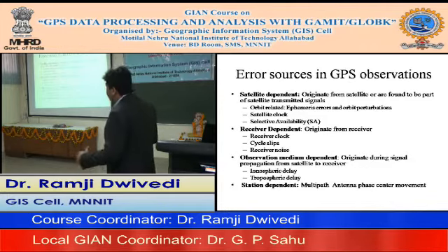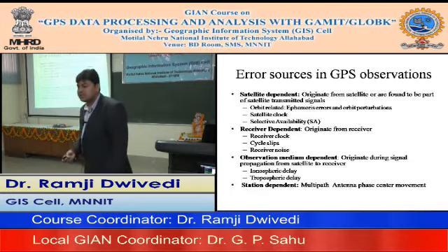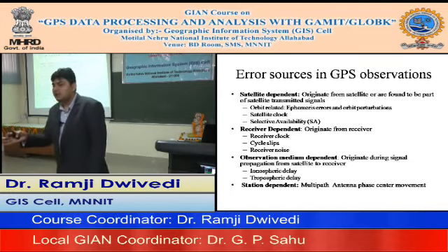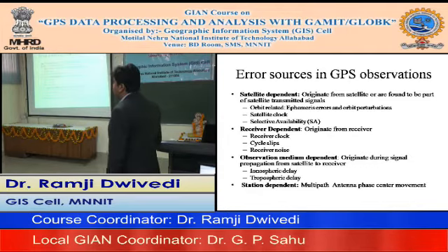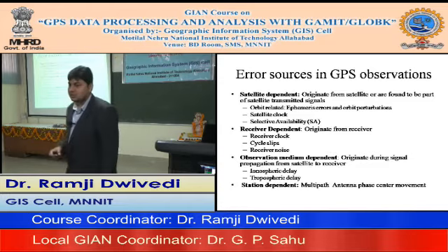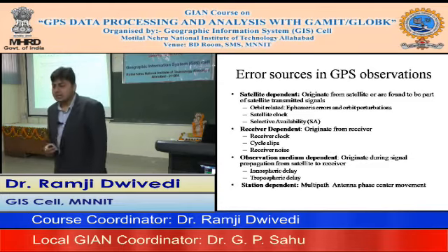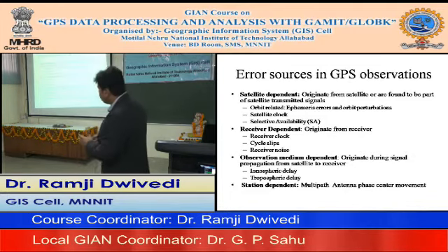These originate at the satellite end and are part of the satellite transmitted signal. The navigation message coming from the satellite carries information about the ephemeris. If you use this broadcast ephemeris to generate the satellite orbital estimate for the position of the satellites, you could see the effect of those errors. We'll also see some graphical representations of those errors.